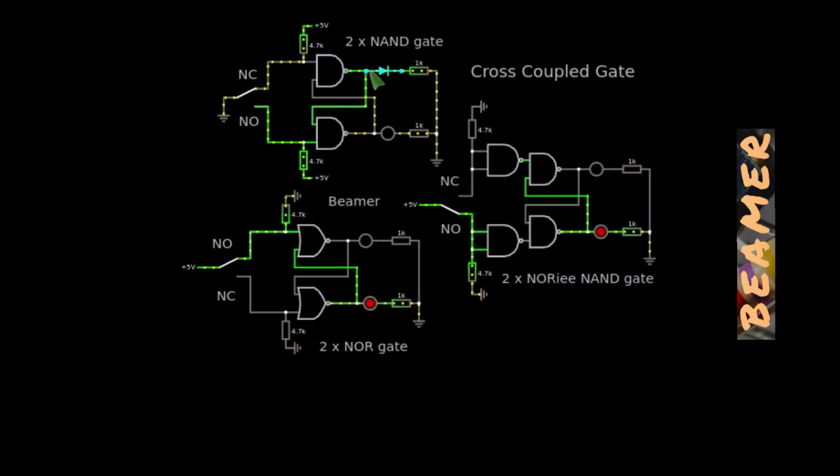The 1 is driving this LED, which is the green LED, and I'll tell you about that in a second. So the 1 then gets transferred to the input of this NAND gate. There's a 1 there and there's a 1 there, so therefore that is at a 0. The 0 then gets transferred through to the input of there, and the system is now completely locked.